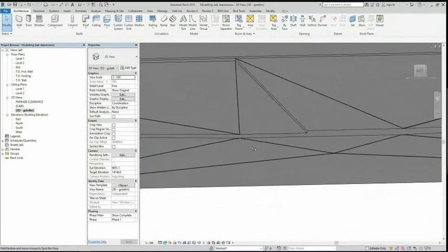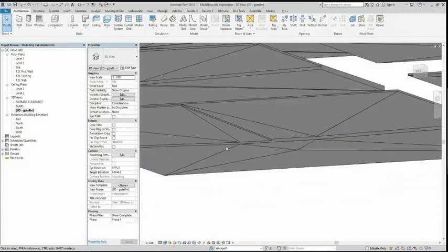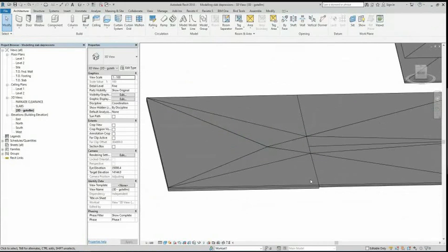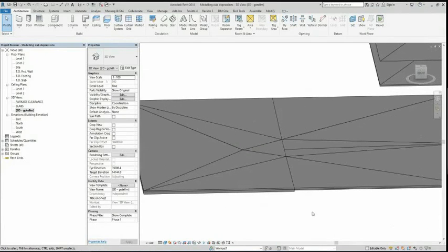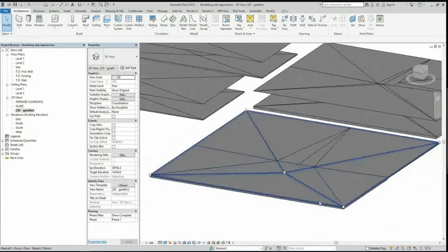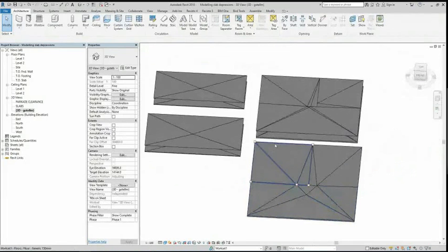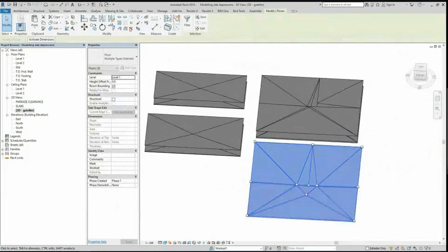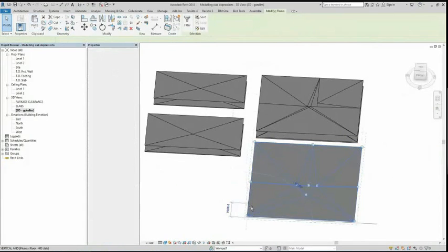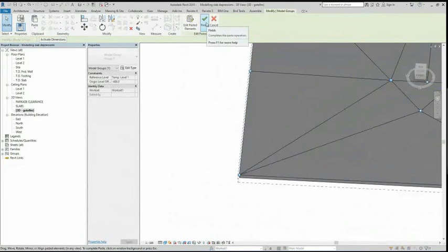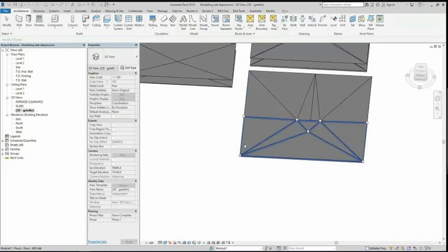So if you're working in any sort of space where you have this parkade clearance created below this slab, now you can also represent different slab thicknesses for the floor above that would affect this annular space between a parkade clearance below here, theoretically, and the slab above. So again, I'm just going to delete that sacrificial floor element, and now I just have the 3. So same thing with the single floor slab. I'm just going to copy all 3, or select all 3 at once, copy, paste, make sure that it's lined up, and so there's no offset, and paste, finish, and it says my floors overlap, which is fine.